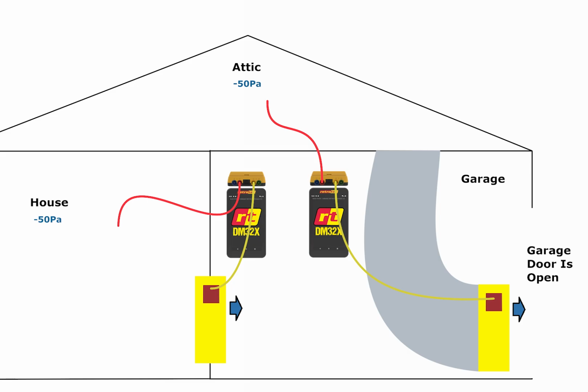And then on the duct going back into the attic, that red tube is going to reference back into the attic. The main reason for this is that when you're using Fantastic, or really when you're doing any kind of blower door test with multiple manometers and fans, you always want all of the gauges inside or outside.